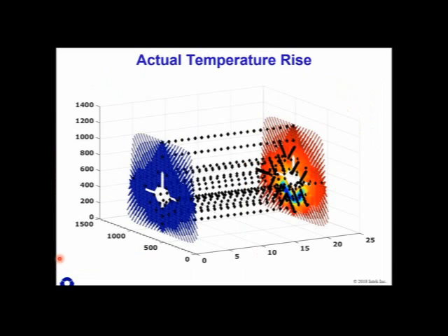Yeah, this one here, this is a Westinghouse. This one's really cool. Okay, so we've got another way to do temperature measurements. We can actually measure temperatures inside the tubes. Now, we wouldn't recommend this for just somebody doing performance evaluations. This is a very specific need for this very specific project, that we wanted to have temperatures of the cooling water inside the tubes along these 75-foot long tubes.